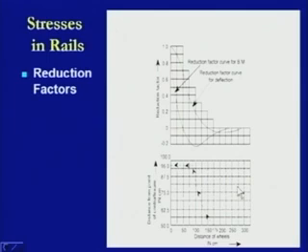Now, what we have to do is find out this distance from the point of contraflexure on the basis of the value, as we have seen previously while computing the bending stresses or the bending moment, where x is computed.